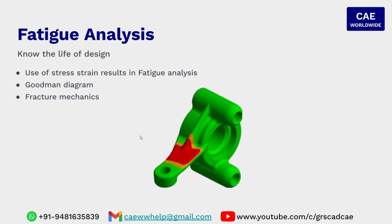Then we are going to discuss a very peculiar analysis, that is fatigue analysis: how to use the stress and strain results in the fatigue analysis, Goodman diagrams, and a little bit about fracture mechanics. Whenever a body is subjected to repetitive loading, the body is going to experience bending continuously, which is going to lead to the failure of the part.